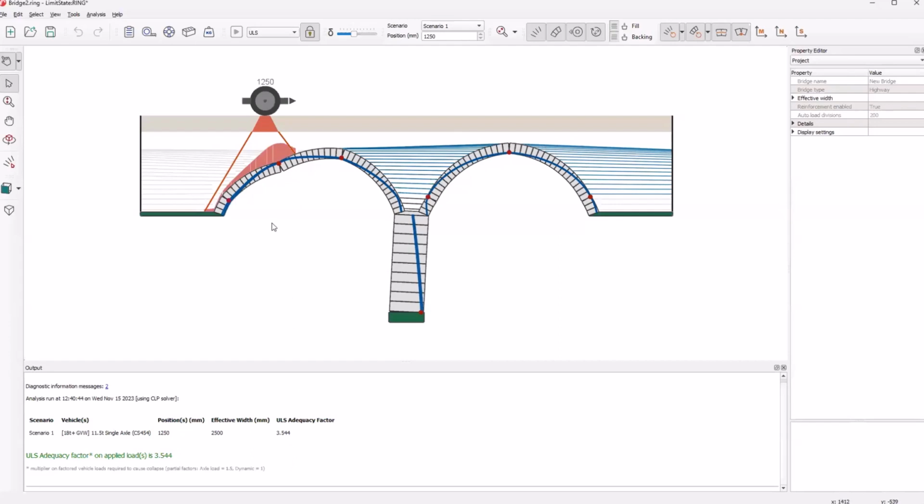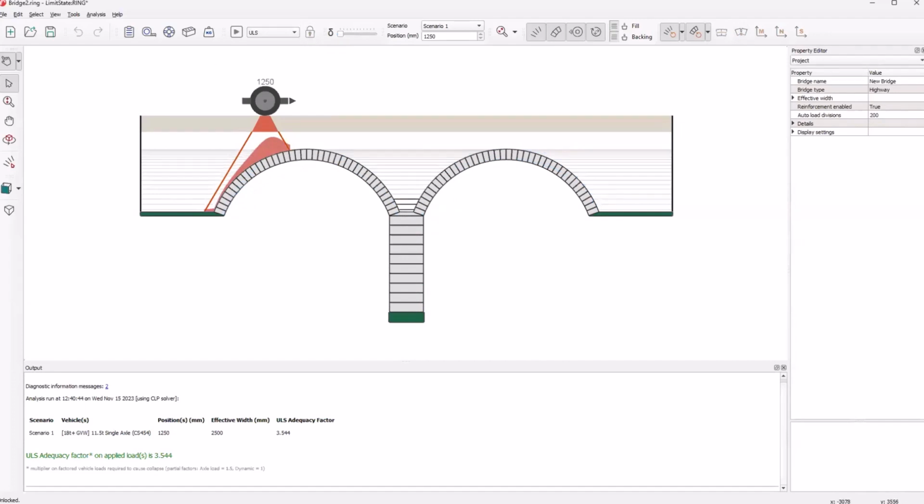Now, before I go on to the vehicle details, I'm going to model a detail of this bridge which I wasn't able to replicate in the wizard. So what I'm going to do is enter the presence of some weak masonry. Perhaps they've got a different construction near the top of this pier. I'm going to say that the crushing strength of that masonry is, say, 2 rather than 5.